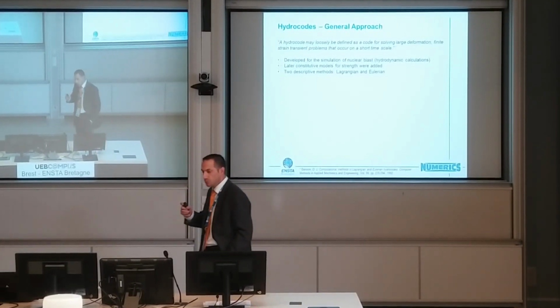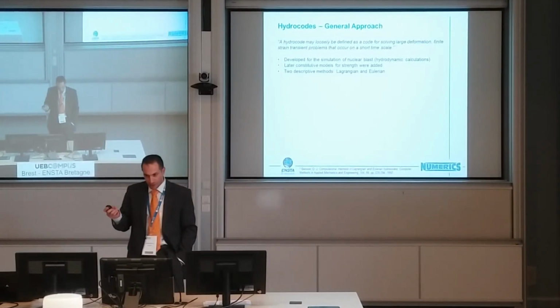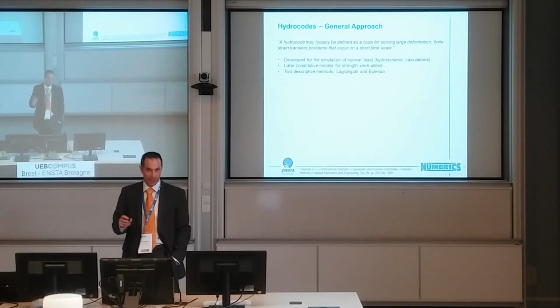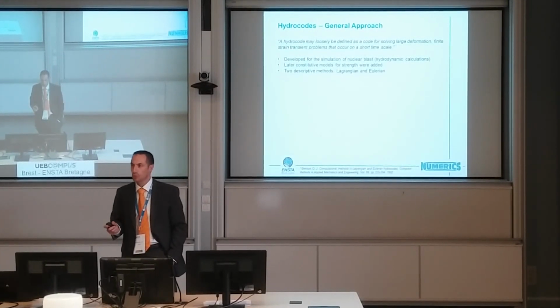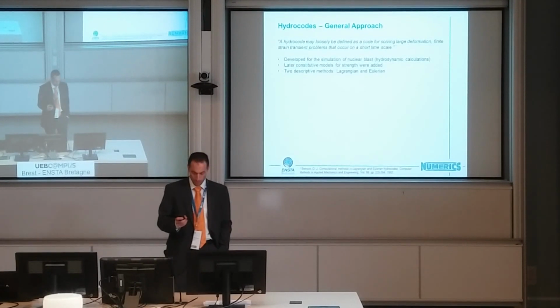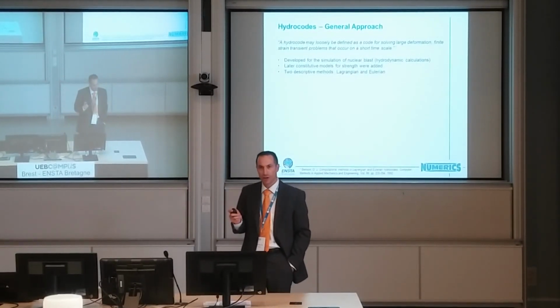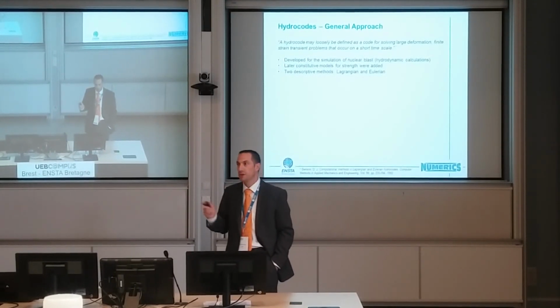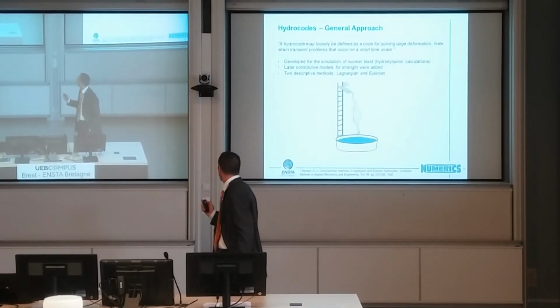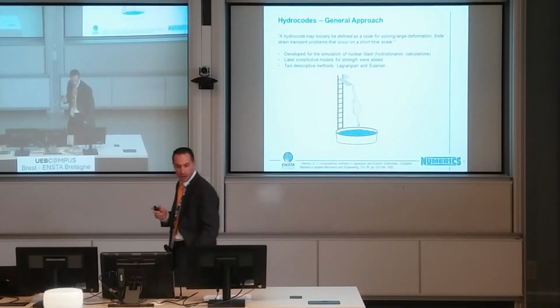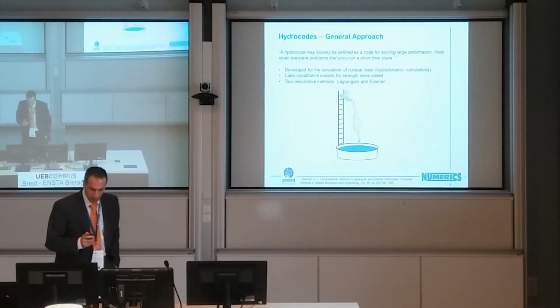So now we can simulate not only hydrodynamic events, but also strength effects of all types of materials that are loaded on short duration. Generally, there are two descriptive methods in the hydrocodes. There are more, but the most basic ones are the Lagrangian and the Eulerian.